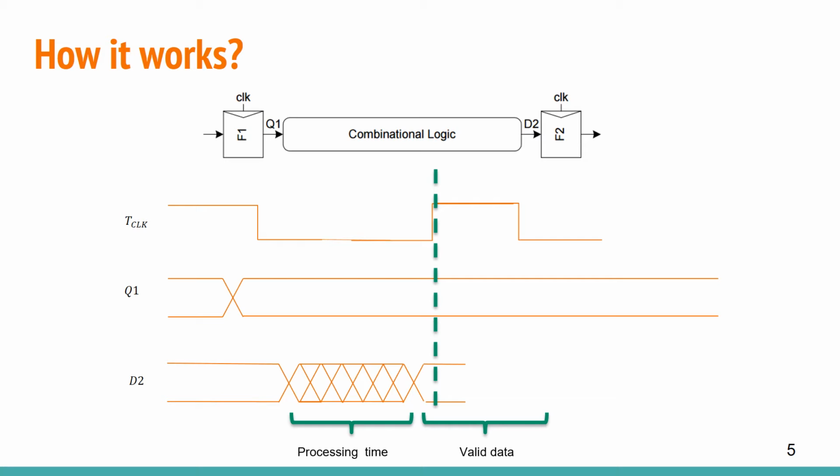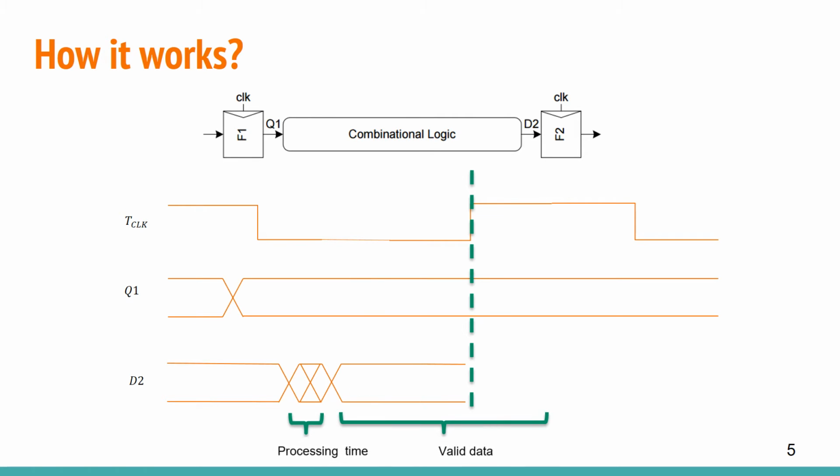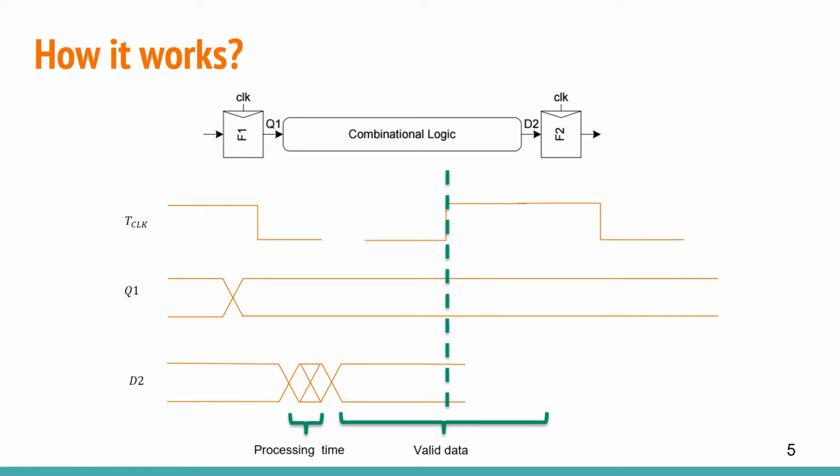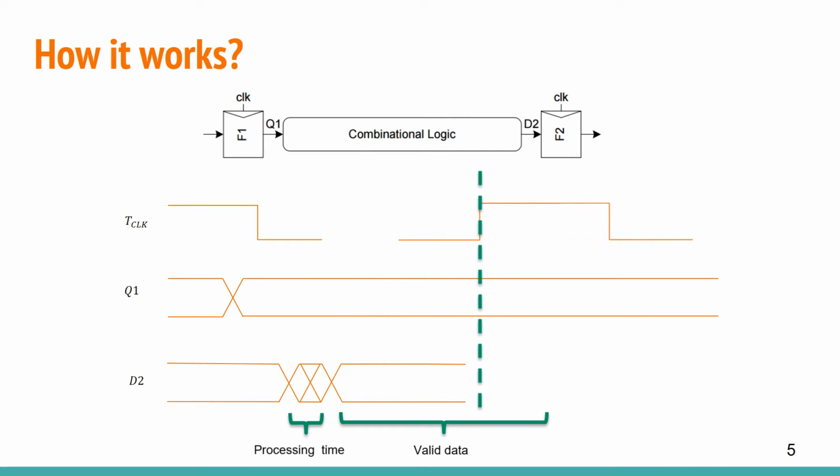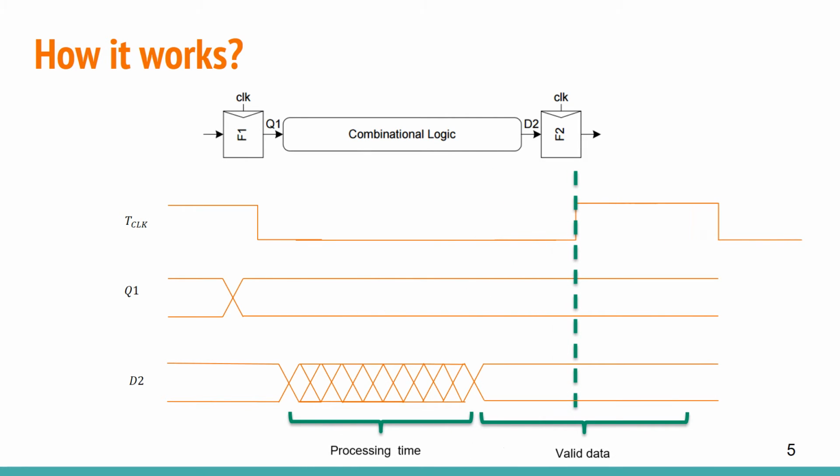Let's now return to the reference case and see how it improves increasing VDD. Notice that changes are not in scale. Well, now, with increased VDD, we can also increase the frequency and we obtain the best improvement. Okay, now we change the problem completely and think that, for example, we send an email. In this case, it does not matter if it arrives in a few seconds or in 5 minutes, so we can reduce VDD and frequency.